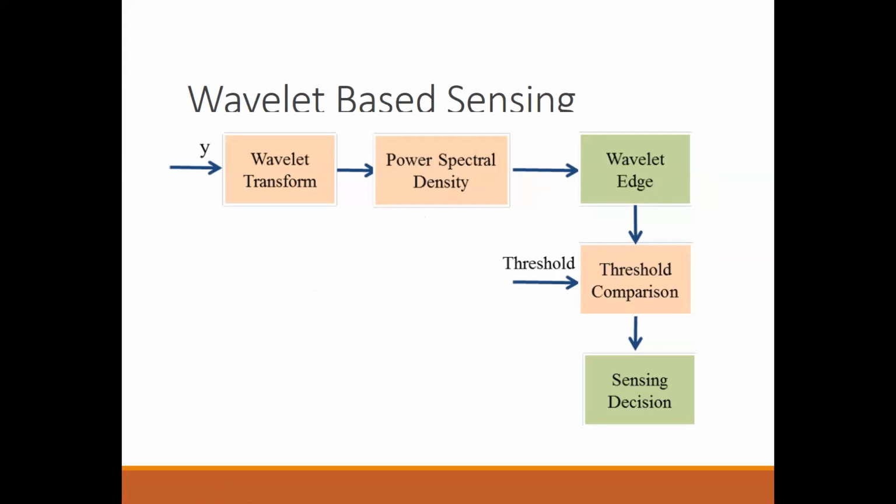I hope many of you might have come across the wavelet transform either in image processing or in some other context. Essentially, the Fourier transform is trying to decompose the signal into multiple sinusoidal components, every minuscule amount equal to one frequency sinusoid. But in the wavelet, we are trying to decompose the signal into several wavelets, where you can control the wavelet in time and frequency.